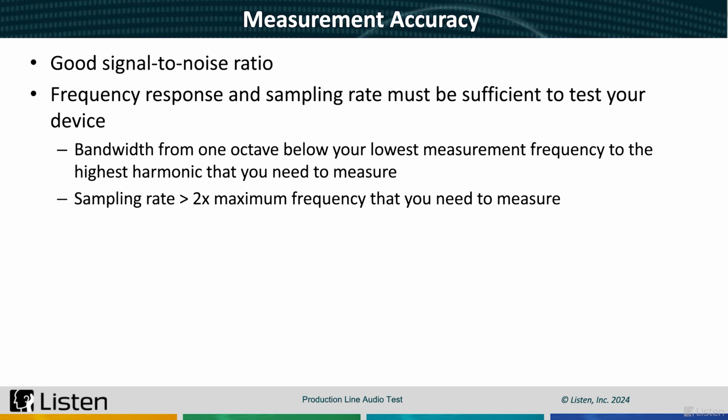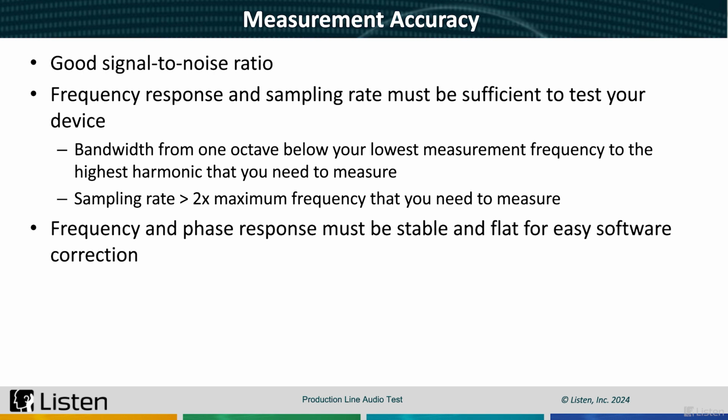It's also important that the frequency and phase responses are stable and flat enough that it is easily corrected for in the software. We typically suggest an audio interface with an ASIO driver for consistent and repeatable latency. Good signal path calibration of microphones and mouth simulators is also essential for accurate results.